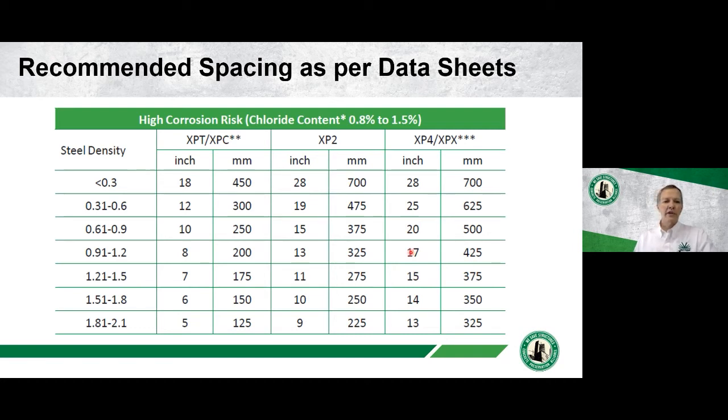It doesn't matter which of these options you pick, they're all going to provide equivalent protection, and that's going to come down to what your preference is or the contractor's preference in terms of how they want to install on the job, or maybe what the rebar spacing is and what matches with that.